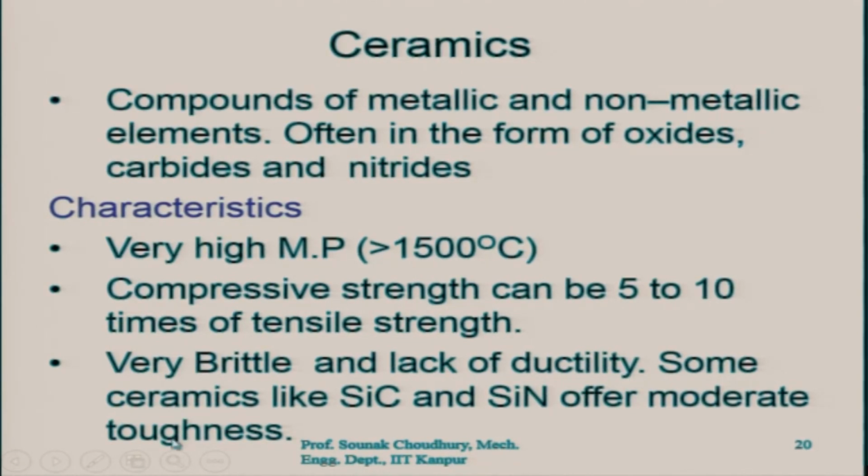Some ceramics like silicon carbide and silicon nitride offer moderate toughness. They can reasonably well withstand shocks. Overall, though, ceramics are not very good shock absorbers. For example, in machining, the tools are made of ceramics, but those tools cannot withstand the vibration in the machine tool.